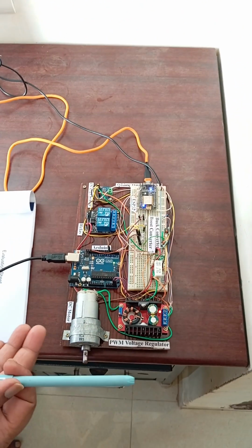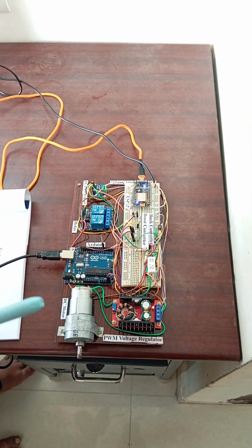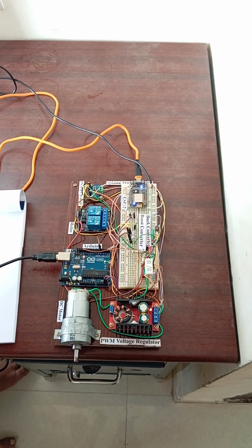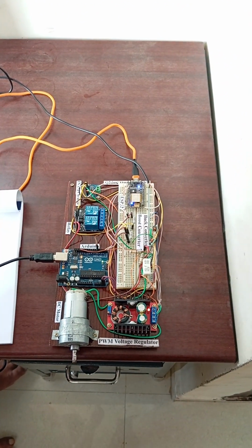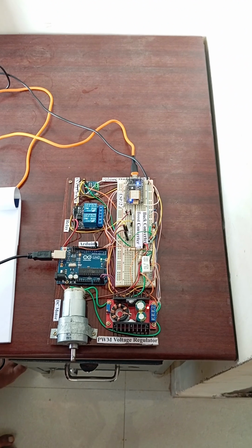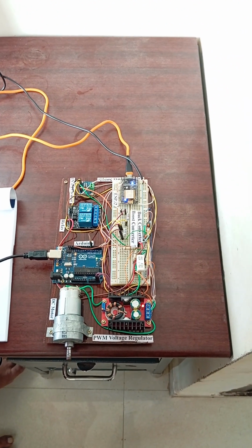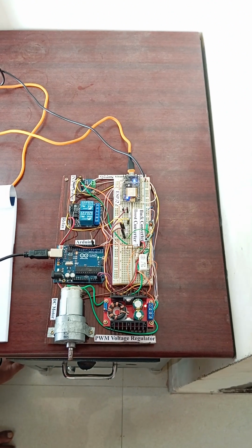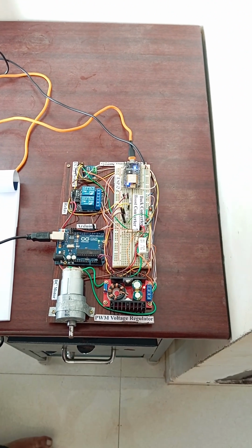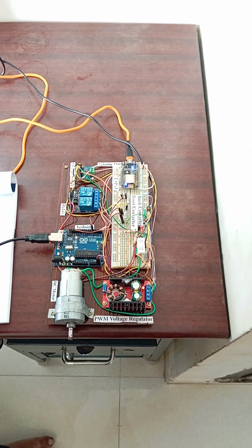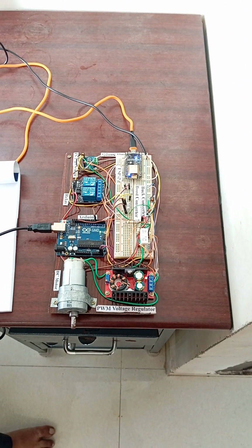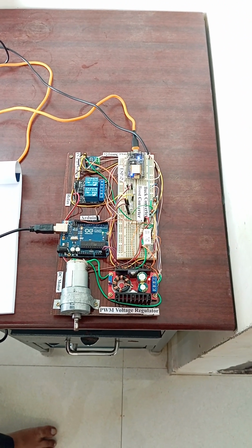Once the cloud transfer has taken place, the processing is done, and depending upon the thresholds we set, that is 12 volts for over voltage and 450 milliamperes for over current, the actions will take place, and accordingly the relay operation will take place. Over this project we have conducted a number of case studies, around 6 case studies. In each case study the voltage is varied in 5 steps of 1 volt.